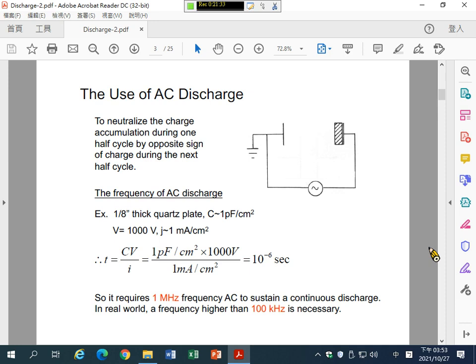plasma properties. For a low frequency power supply, once the plasma is generated, the ion energy and the electron energy inside the plasma will be higher than in plasma generated by a higher frequency, for example, a 40 megahertz power supply.